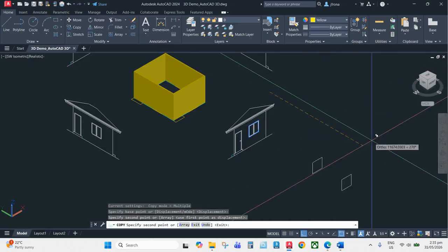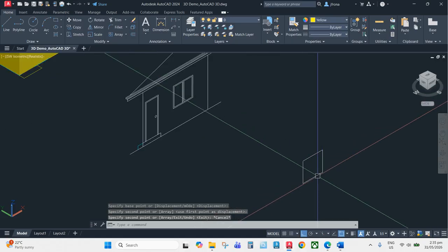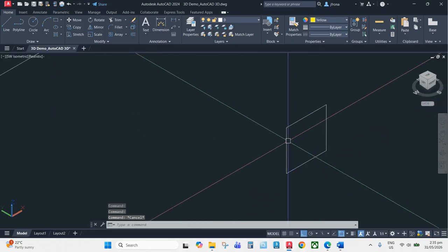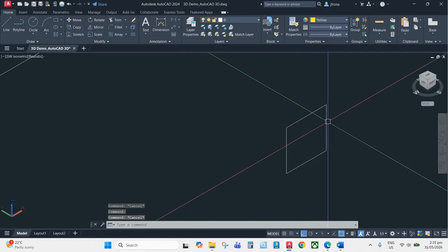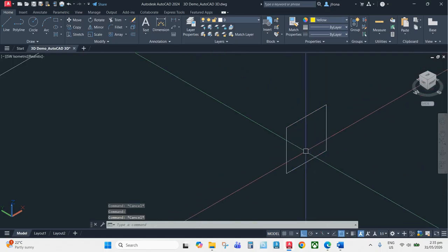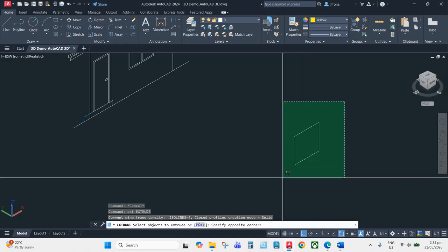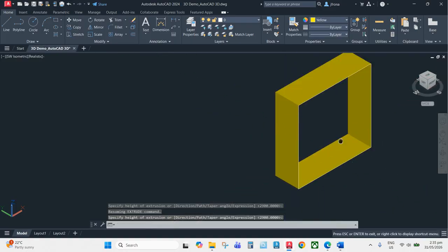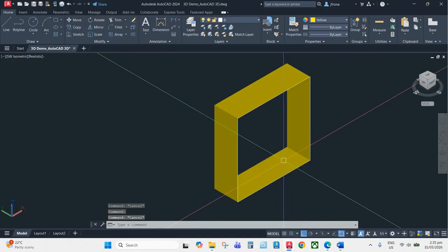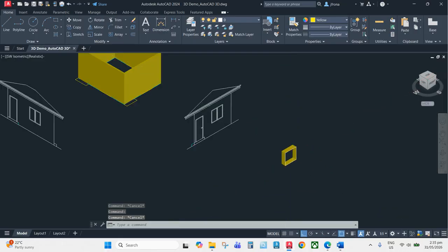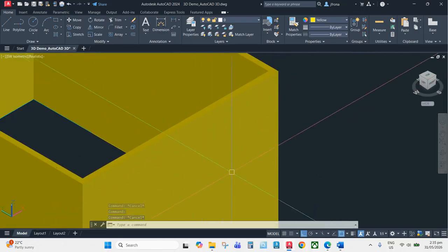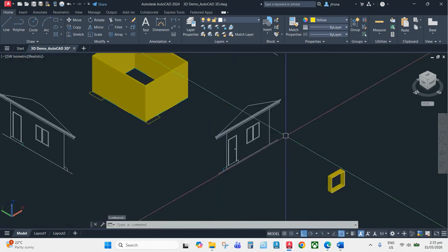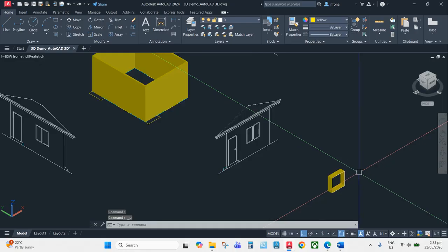Before you extrude, like I've mentioned earlier, your object should be one entity. You can extrude this, right? But it's going to be a mesh. It's not the proper way of extruding when you're going to use that to create a void. It's not going to work, the mesh.